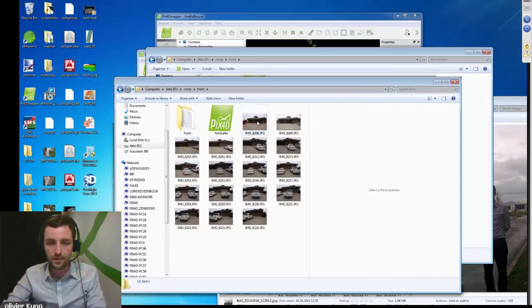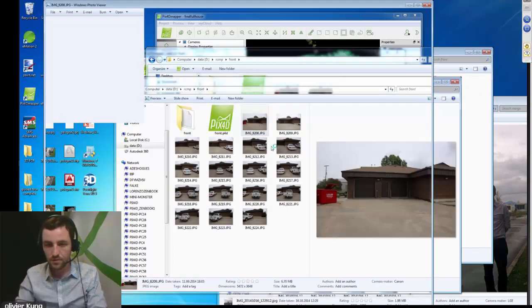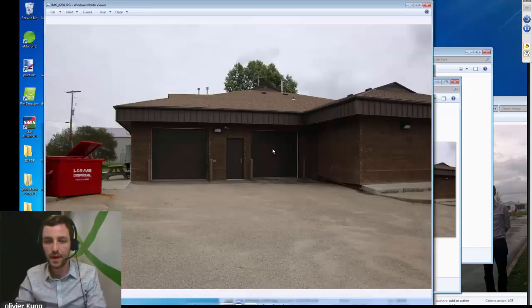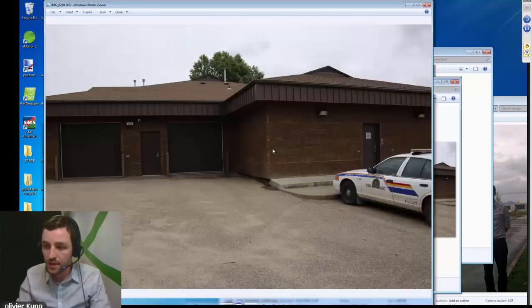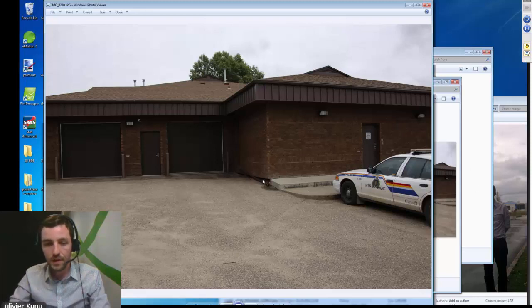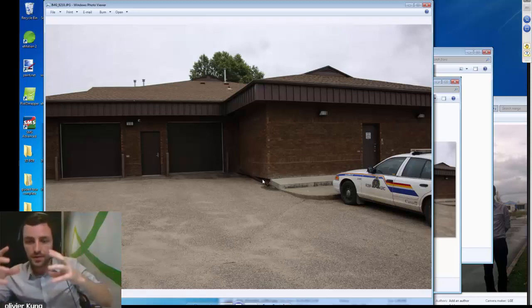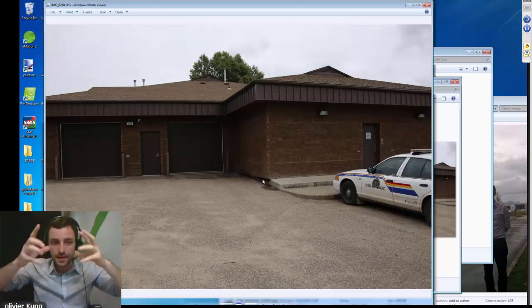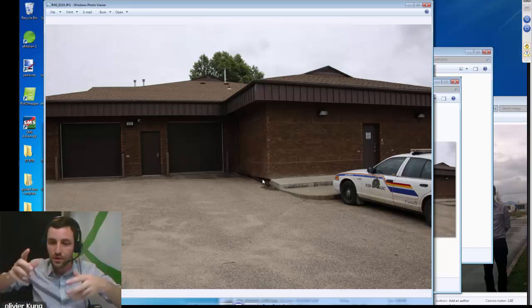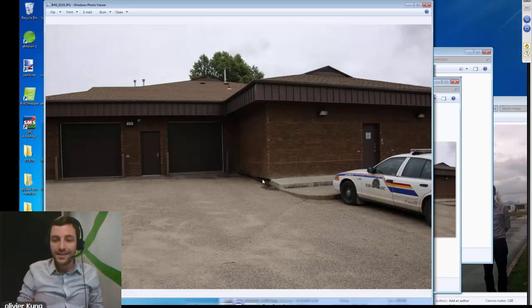So this would be the front data set. These are pictures taken by a Canon 5D camera from the ground. Very important when you take pictures from the ground is to move every time you take a picture. If you stay at the same location and change only the orientation, you are adding inaccuracy to the whole project.